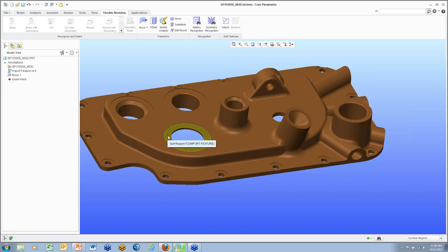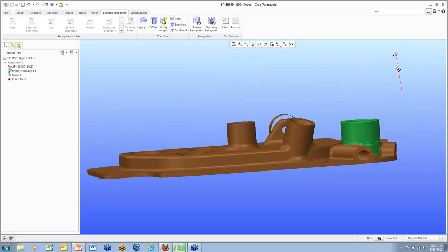So speaking of parametric modeling tools, there's a lot of similarities between working with a parametric tool such as Creo Parametric as well as SolidWorks in terms of how to mirror something. So let's say we want to actually mirror this boss right here. Okay, how are we going to do that? Well, we're going to have to select a mirror plane.